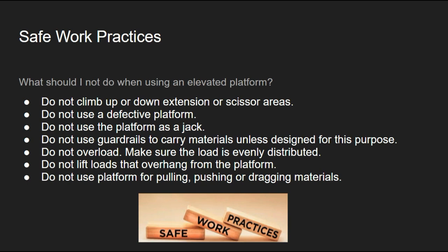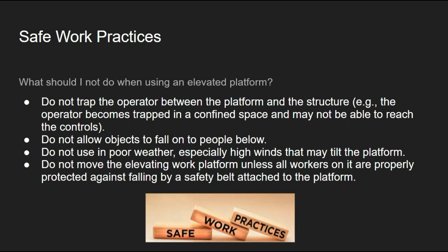Do not use guardrails to carry materials unless designed for the purpose. Do not overload. Make sure the load is evenly distributed. Do not lift loads that overhang the platform, and do not use the platform for pulling, pushing, or dragging materials. Do not trap the operator between the platform and the structure. The operator becomes trapped in a confined space and may not be able to reach the controls.